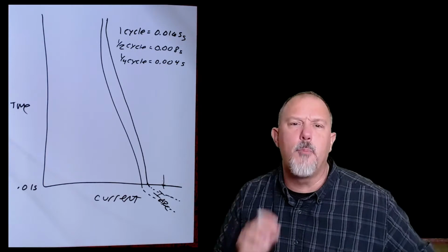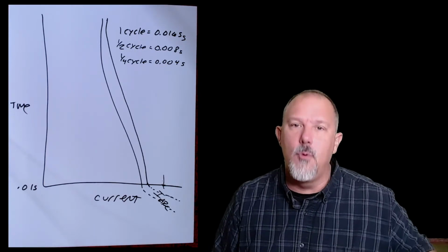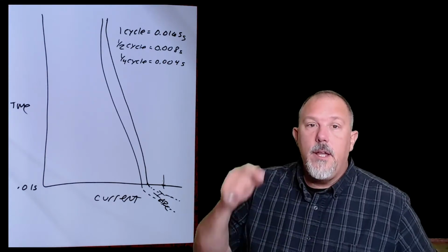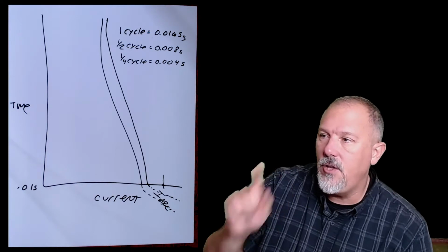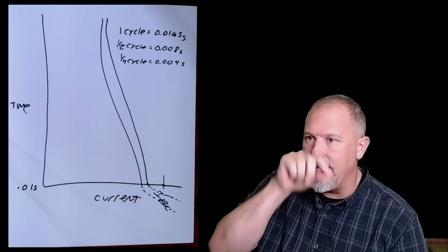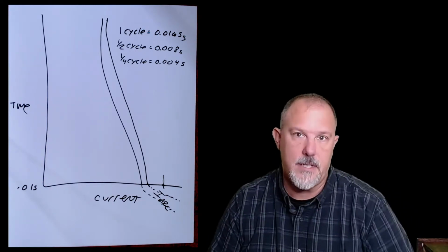You know what a fuse eats for breakfast, lunch, and dinner? Never gains weight. The more of it, the more they love it. Current. So a current limiting device, can we use it to change the available fault for selective coordination? I'm going to get to that one. How about incident energy? You don't change the available fault for incident energy.